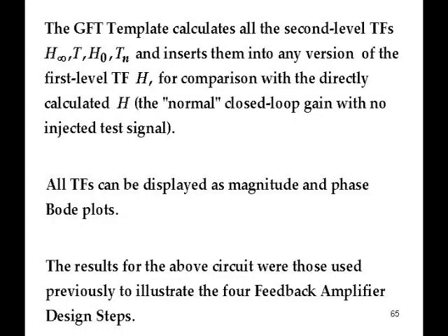It also calculates the original circuit gain without any test signal injection at all, just so you can check that the theorem gives you the right answer. You can display all the transfer functions as magnitude and phase Bode plots. And in fact, those are the plots that I used already when I was describing the steps that you go through. And here's a few more of the individual results.